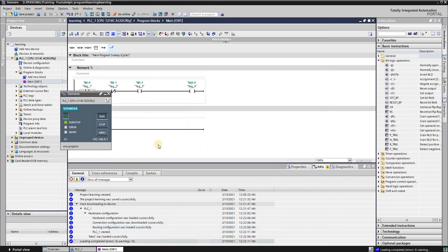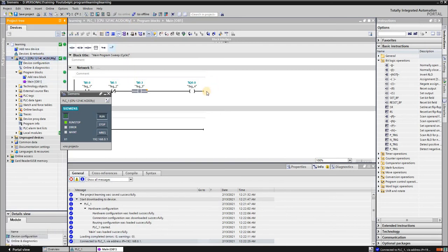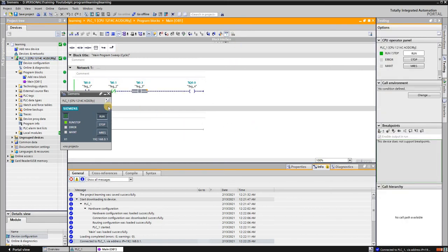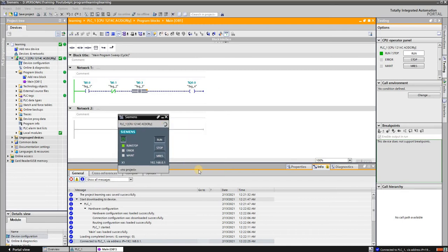First, simulation testing your program, there are two ways. Either you can modify the blocks here, which I don't want to do first because I prefer the other way. You can go online as well here. Right now the coil is closed because we don't have any input, we don't have level switch feedback also. The more efficient way of testing a program through simulation is creating a simulation chart. This is how you're gonna do it.